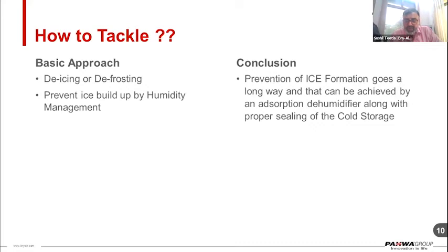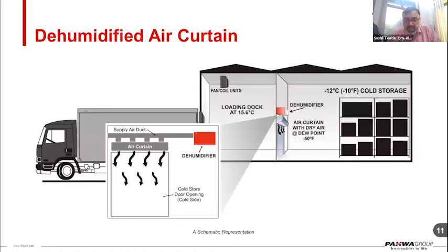Along with the consultants, we are working very closely with the industry to provide solutions as per their product requirements. At the areas where we have to open the doors very frequently, or the door is open for a longer time, there is another solution which we provide to our customers. It's an air curtain in combination with a dehumidifier. The air curtain is provided on the top of the door, and the dehumidified air comes in that curtain, and that eliminates or minimizes the possibilities of mixing of outside air with the air which is present inside the room. And it's a very, very effective solution.